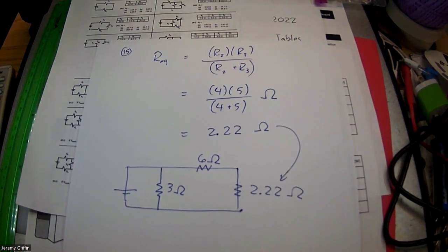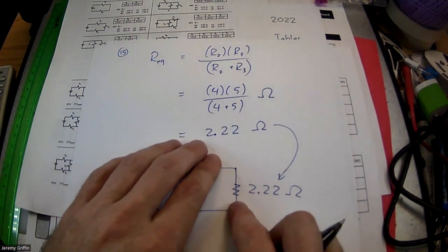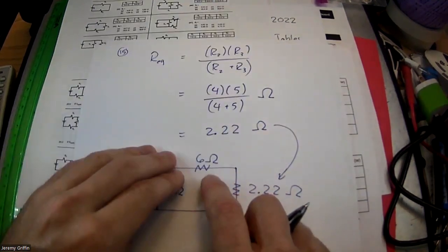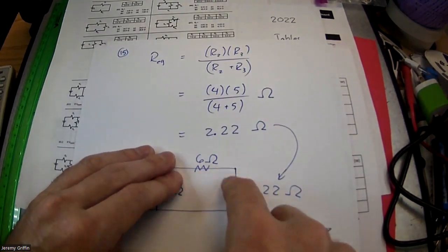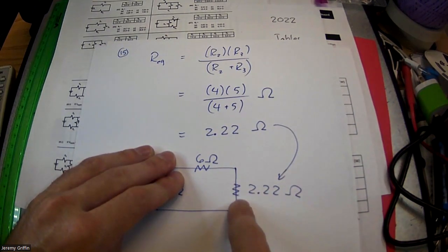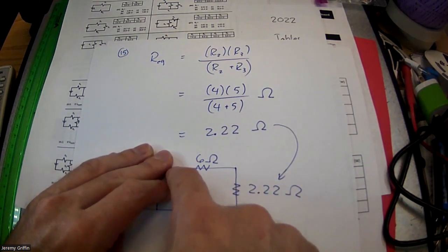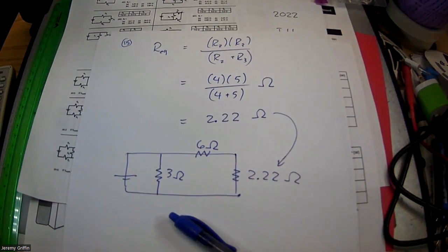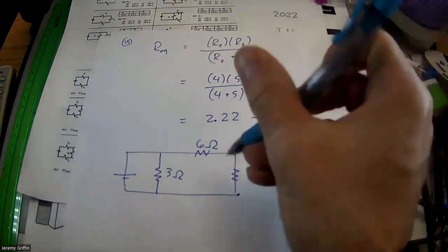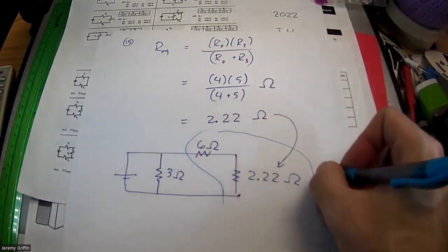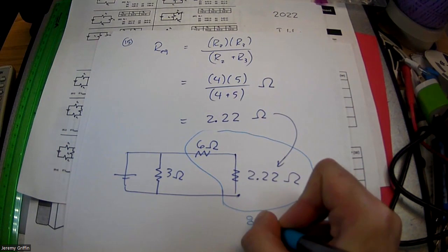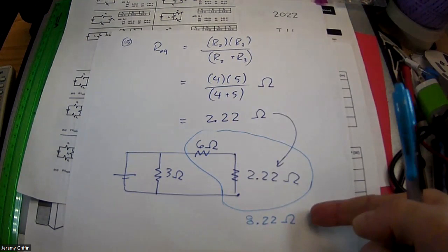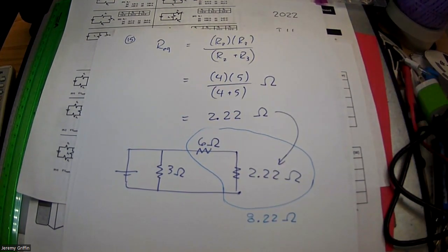Guys hear that? All right, so working back towards the voltage source, the next one I run into is this one up here, which is R4. This is R4 up here, right? Okay. Those two are connected how? Series or parallel? Definitely series, right? It's because it's sequential. Whatever current goes through this also has to go through this. So can I just add those two together? Yeah, that's exactly what I'm going to do. So this looks like this many ohms because I just add them together. That plus that is that. Okay. Then redraw the circuit.